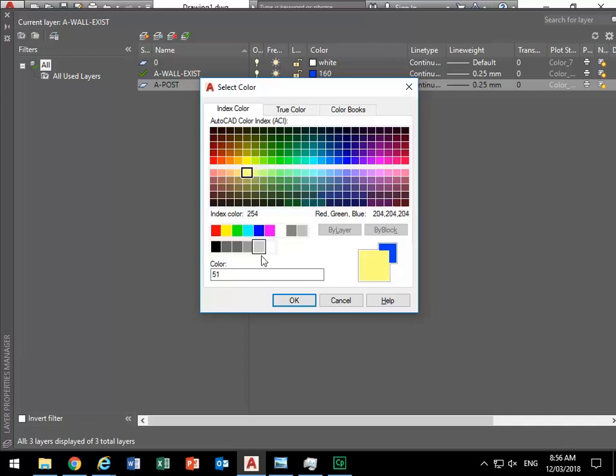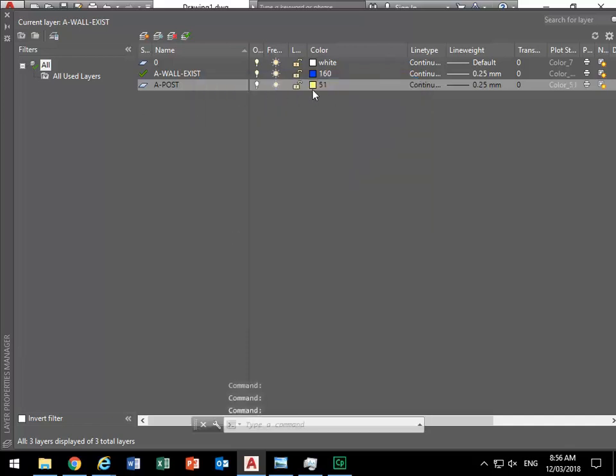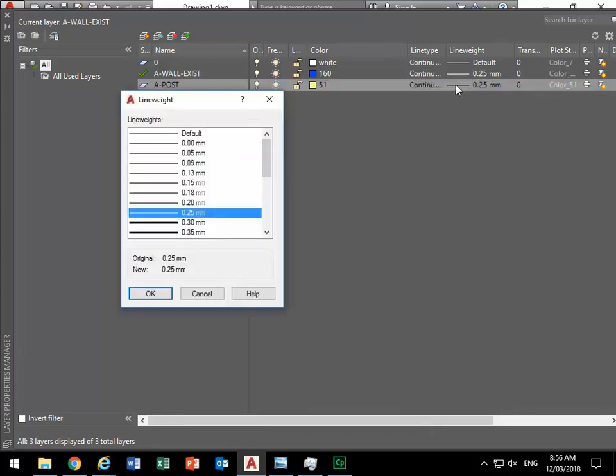Yeah, exactly, that standard, the Australian standard that I showed you. So they're the only really standard colours that you'll find for materials. But again, don't believe those people who tell you there are rules for colours in AutoCAD. It's usually people who aren't that experienced who believe that. Again, they're not going to print, they're all going to print black, so it's just a guide for you, but again, those material colours will help you with some other things.